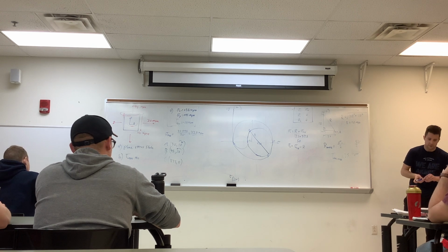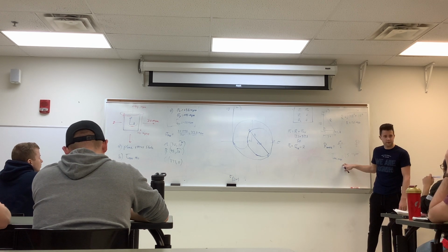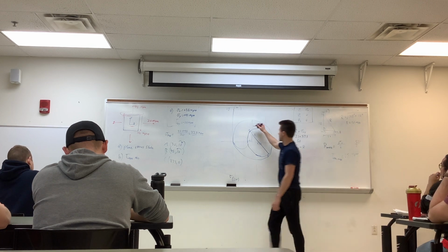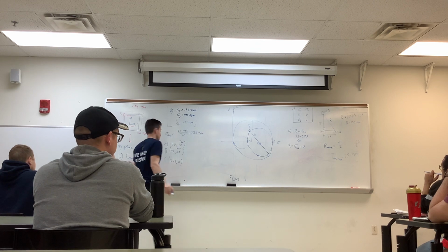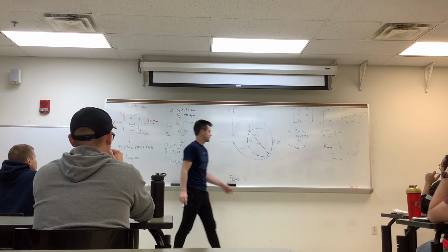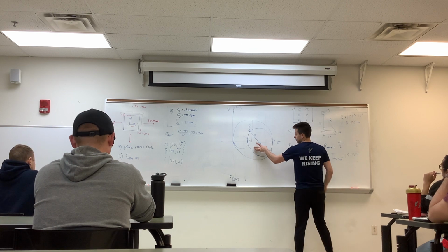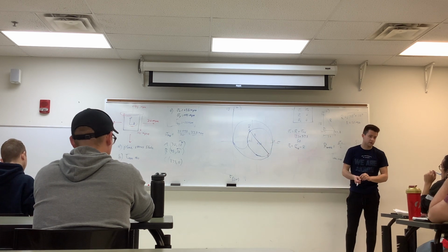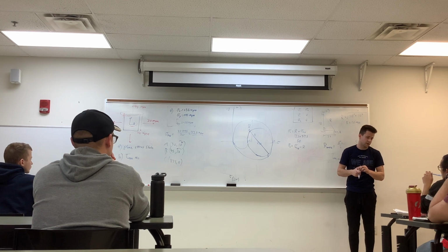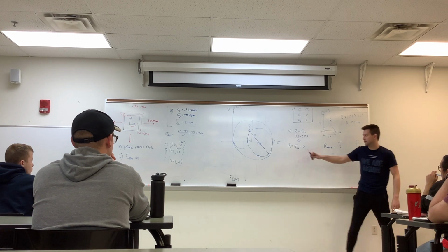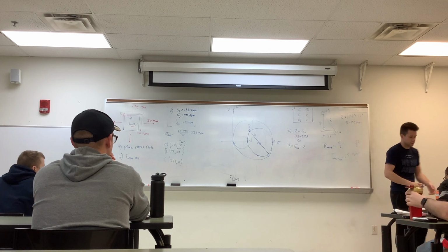Any questions with this one right here? How did I get this? It's this radius. It's the radius of the big circle here. What we were solving for was the absolute maximum shear, which, when I was talking about Mohr's circle, could not necessarily be in the plane of that element. So that is sigma 1 divided by 2, because it's the radius of the big one, between sigma 1, which is the largest number you have, and 0.